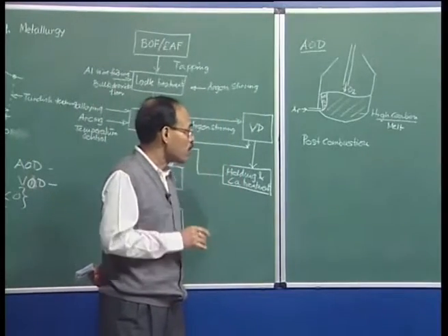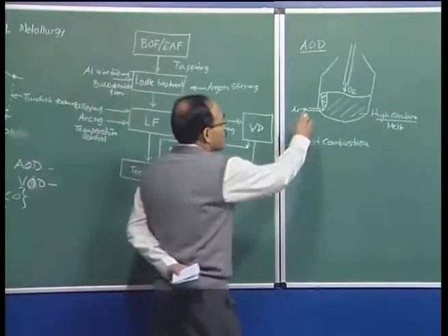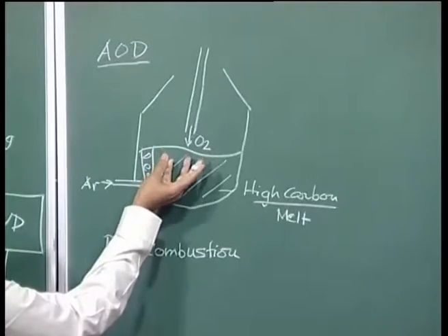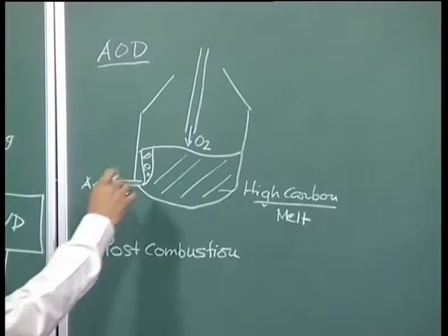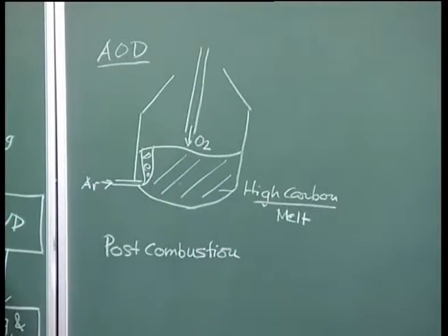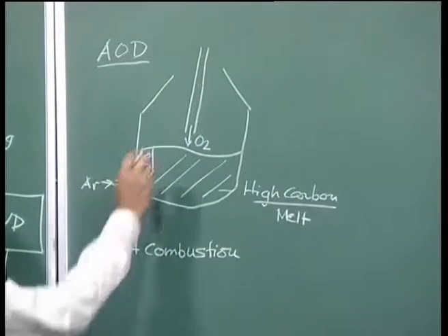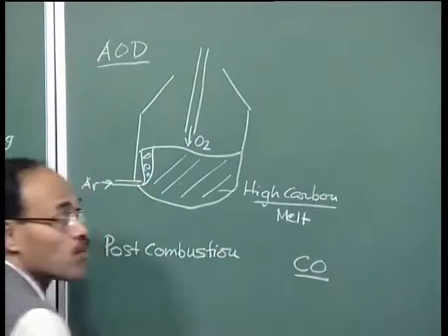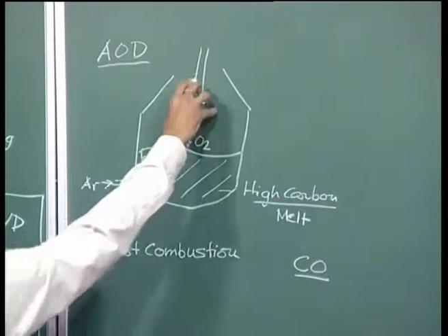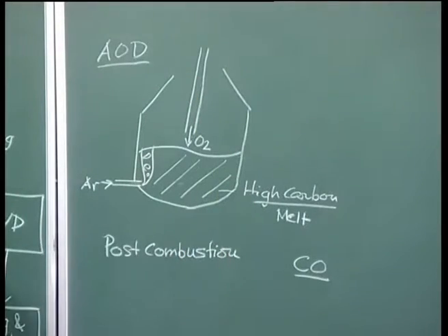Carbon dioxide is not thermodynamically stable, but when the gas rises upward because of its thermal buoyancy, towards the mouth the temperature gets smaller, and if you have a high partial pressure of oxygen, we can oxidize some of the carbon monoxide to carbon dioxide, and some additional chemical heat contained in carbon monoxide can be released within the furnace.